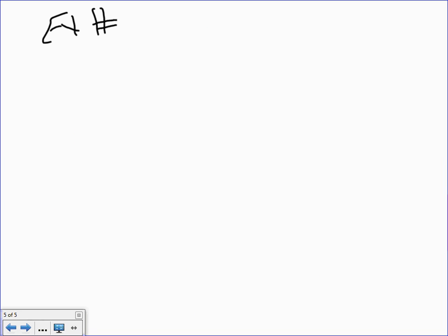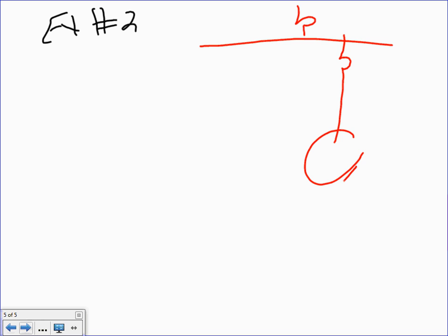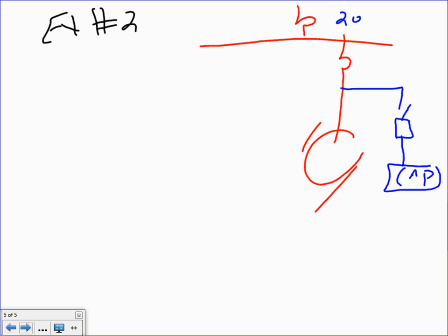Example number 2, guys, the same thing. I have a system, overcurrent protection device. I have my motor, and you get the message here. And I need to come from here, disconnect, fuse, cab. Except this system is 208 volt, of course 3-phase. This baby is 200 horsepower, and it's a 208 volt 3-phase T-frame.